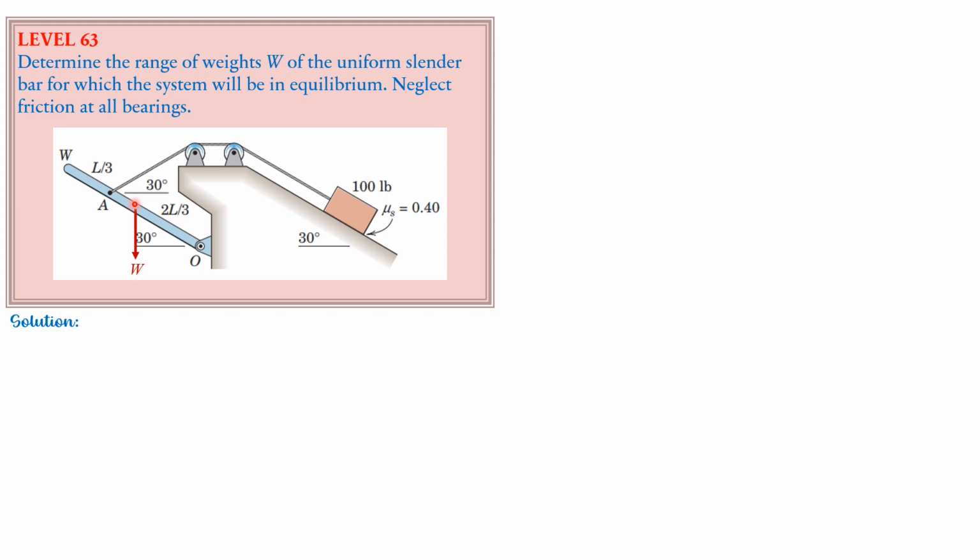Let's have the reactions at O also, horizontal and vertical reactions. The distance of the weight from O is L over 2 cosine 30 degrees.